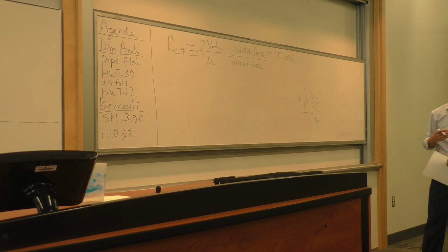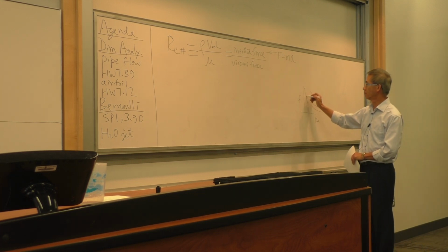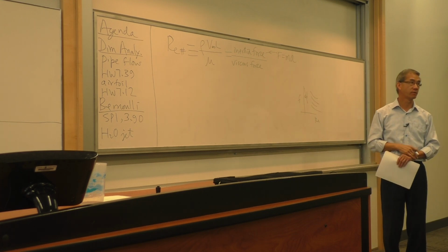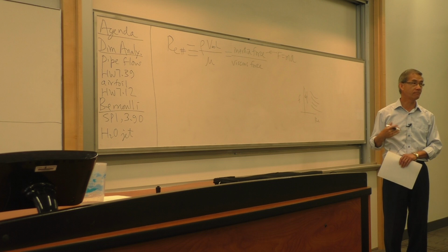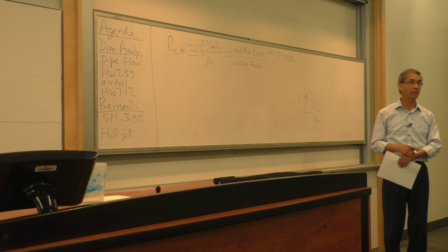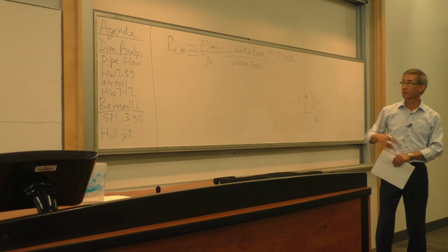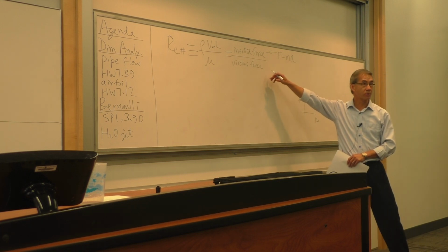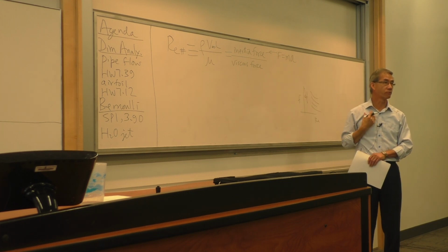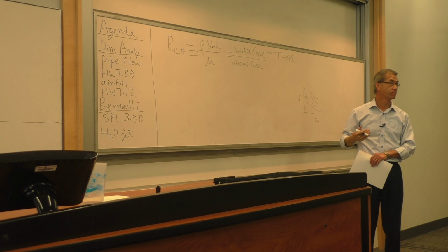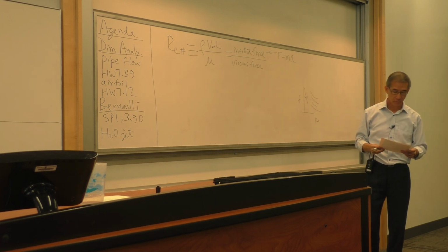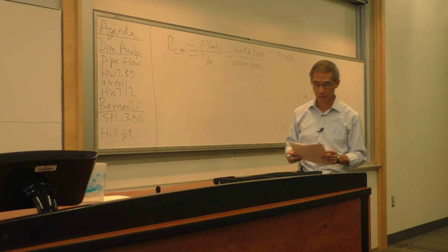So when the Reynolds number is small, it represents some type of flow behavior. In the pipe flow it is laminar. When the Reynolds number is huge, with length scales of meters, 10 meters, 100 meters, like the water that cuts through a submarine or aircraft carrier, that Reynolds number, in the range of millions as opposed to 1,000, will allow me as a fluid mechanicist to picture what the flow is doing. That will be forthcoming when we get to subsequent discussion.